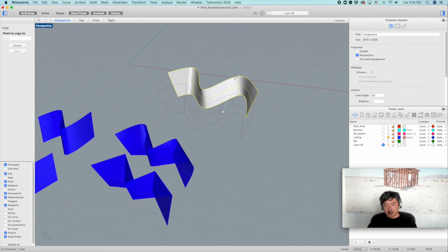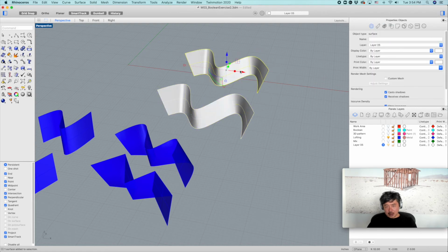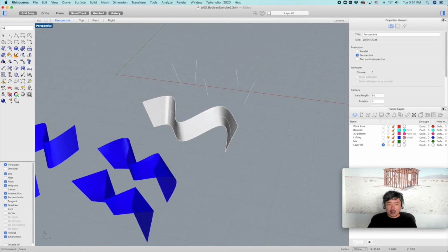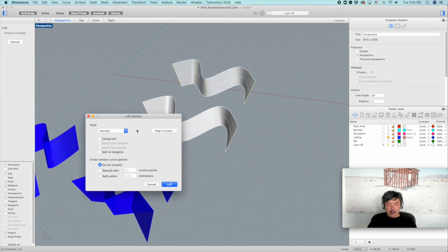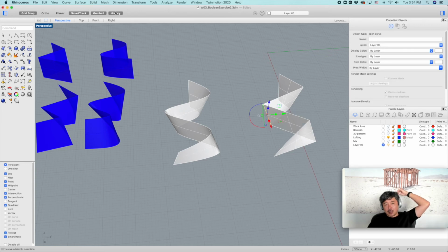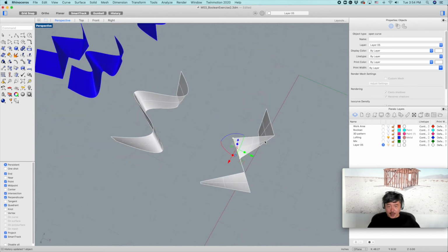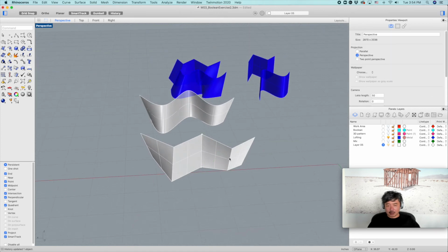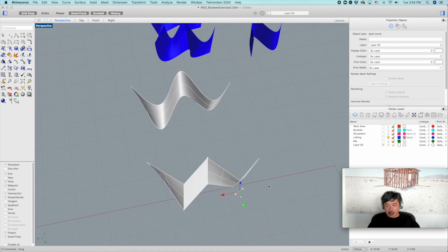In this version, you can just create the same thing using the straight sections. So I'm going to just copy it, then delete this one, and then loft with straight sections. But you can still control it, as long as you have the history on. On Macintosh, it's always constantly on. But on Windows versions, it turns off every time you move it. So you're going to have to click on record history every time you do the loft command, every time. So that's the difference.